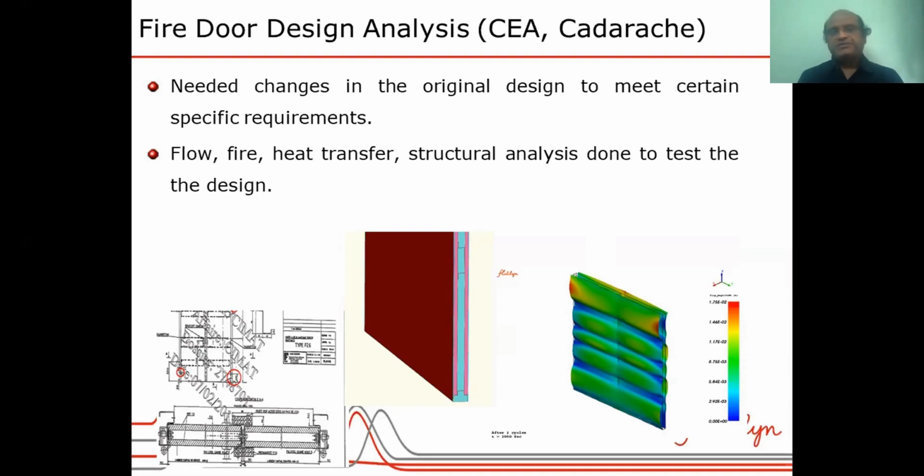In addition to this, these doors should also withstand fire for very long times, maybe 2 to 3 hours, fires at different levels. And in addition to that, they should also be leak-proof. There are certain limits to the allowed leak through the gaps between the doors and between the door and the frame from one room to the other when the doors are closed.